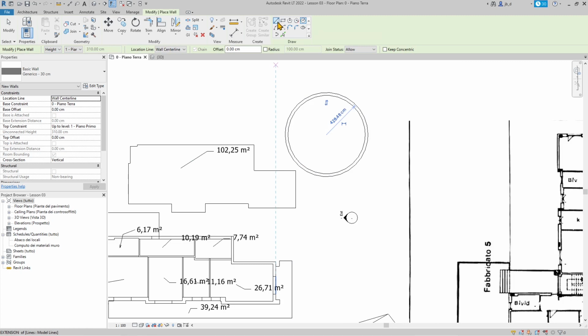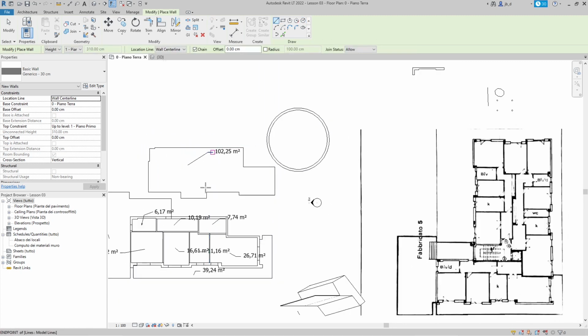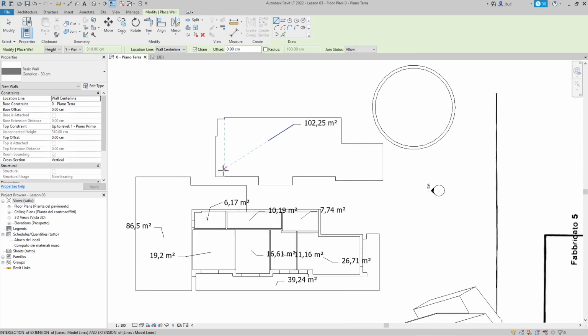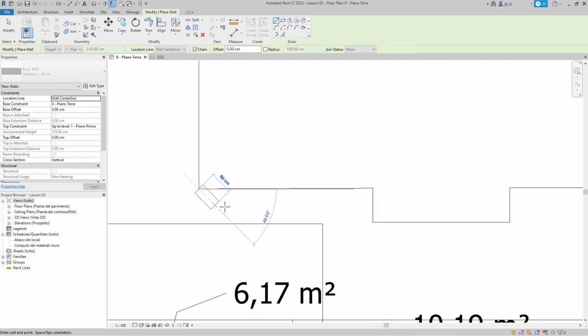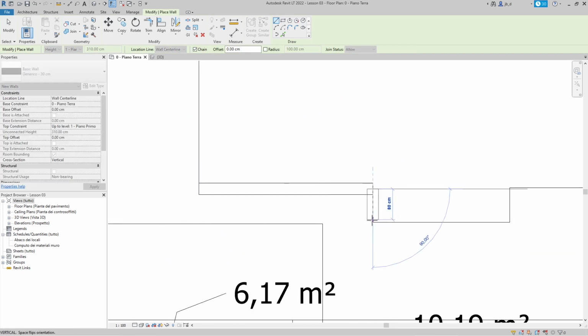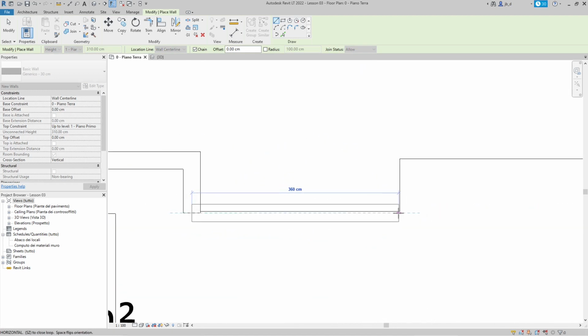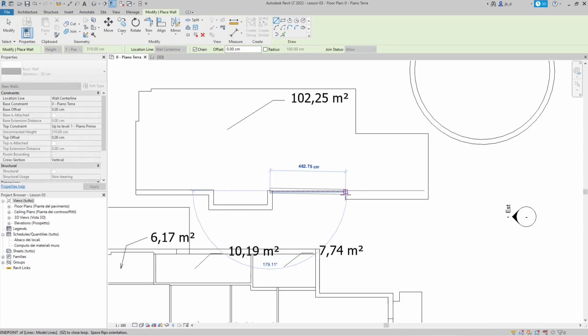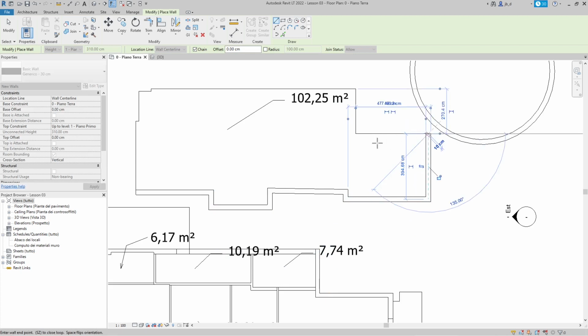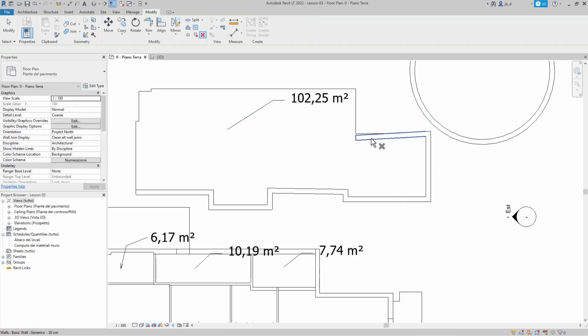And if we use lines, we can, for example, try to trace on the original CAD to create a wall. Now you can see that you can continue, you can use the snaps to be more precise, and you can trace that wall. So use the snaps so that you will be precise. Be careful there. If you miss something, you can just exit and restart.